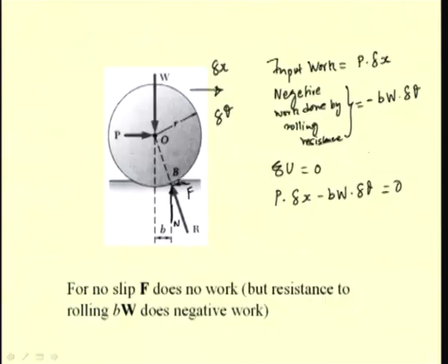And this negative work is not recoverable and it is lost as heat. In case of rolling resistance, again this heat is released by the expansion of this compressed or deformable material. So, again this work is not available.